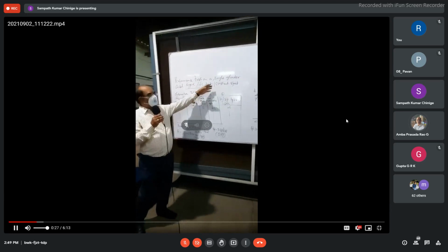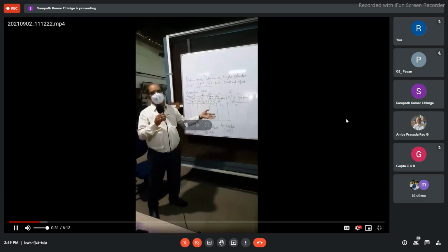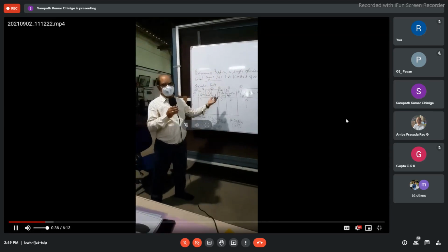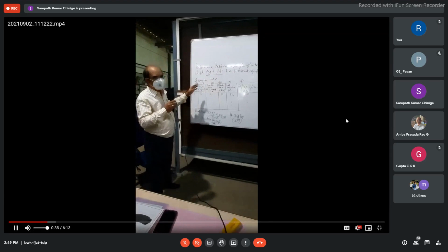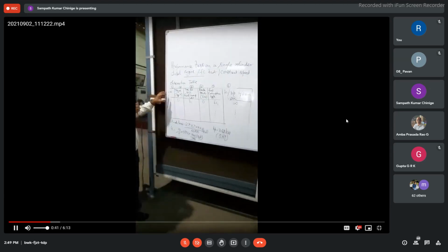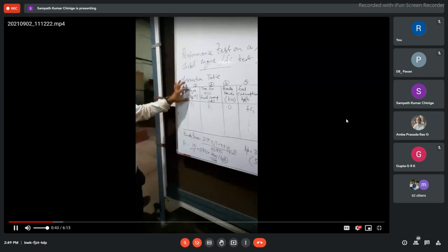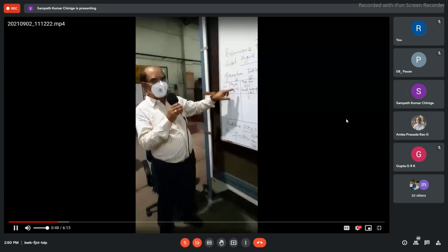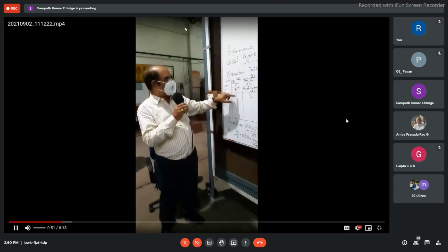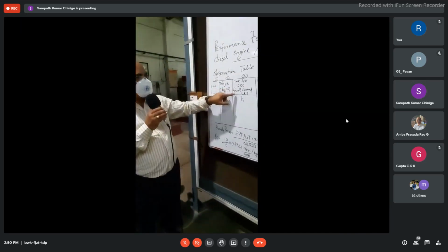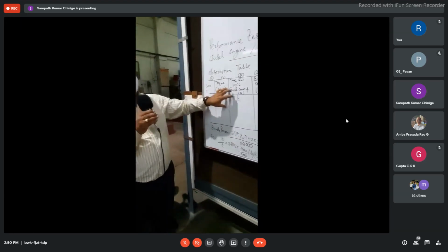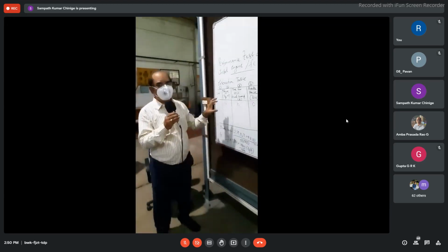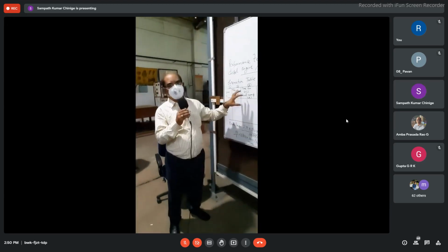And by taking the readings for every torque meter reading, we noted down the time taken for some fixed amount of fuel consumption. So let us tabulate those values. I will just brief you on the tabular column. The serial number is there, then the torque meter reading, which gives the outer dial reading. The larger dial reading gives you the kg force meter, and here we have the time taken for 10 cc fuel consumption. These two are observation values, and in every torque reading we maintain the engine at constant speed, that is 1500 rpm in this specific case.